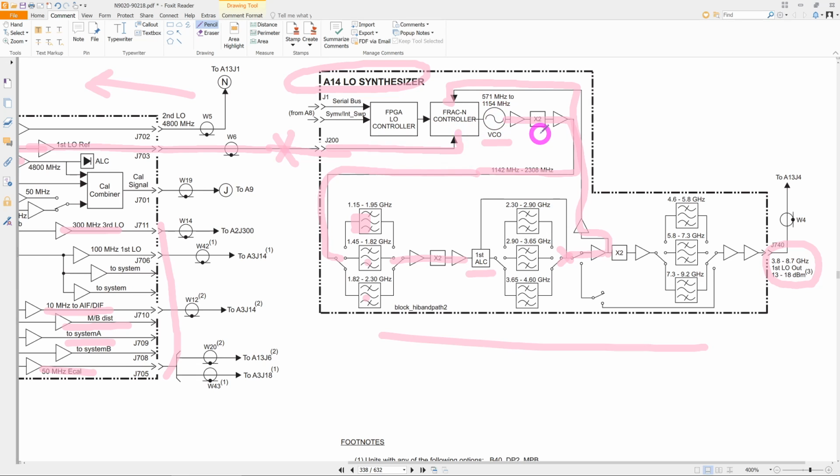This architecture of having a VCO with multipliers afterwards before closing the PLL loop is a really powerful idea, because it allows you to make a VCO at much lower frequency. The disadvantage is, of course, phase noise, because you're multiplying it up passively, essentially. No retiming involved, I mean.